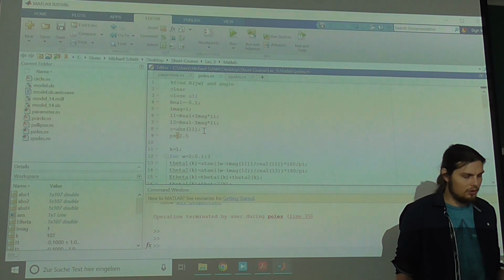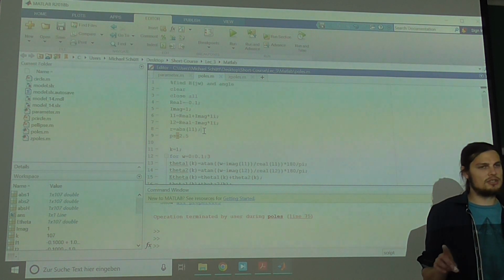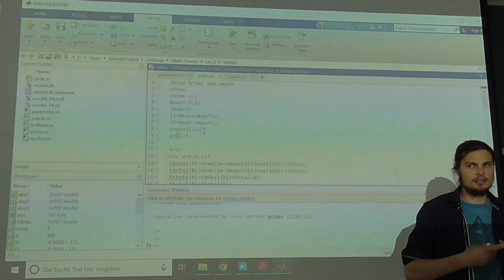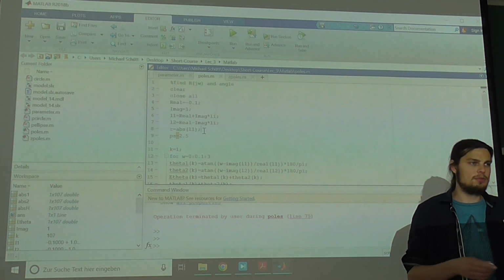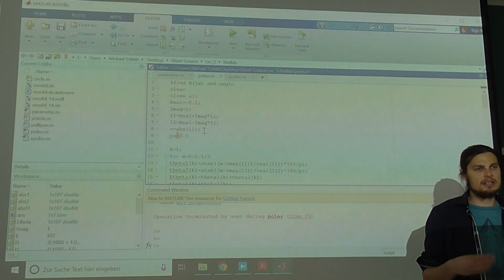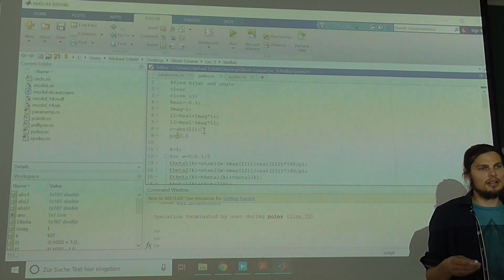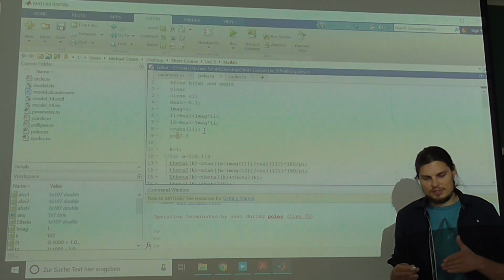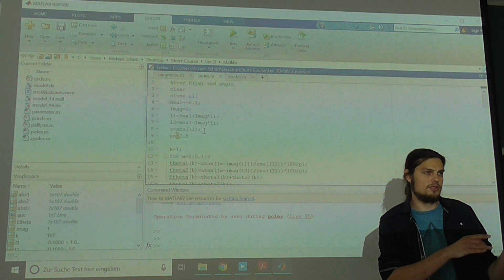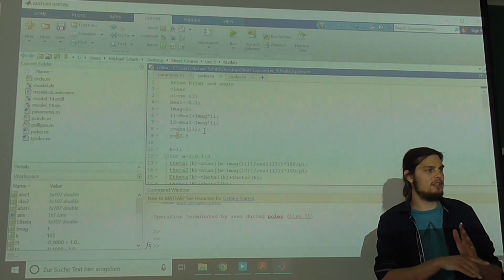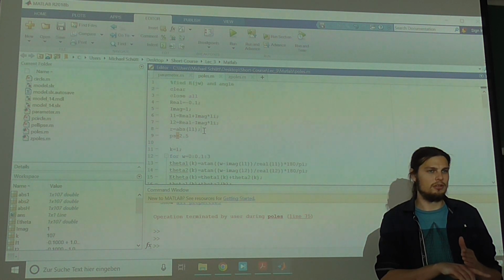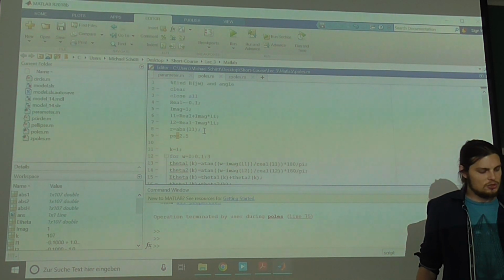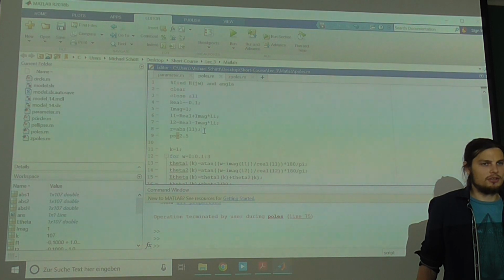So all the continuous stuff that we learn is still valuable and still great to know. In some cases, if you sample very, very fast with respect to your slow system, you can basically call it quasi-continuous, and then you can apply all of these ideas too. But if the tau of your system is too close to your sampling time, then you will see that your approaches won't work anymore. But this is something you have to experience yourself, so I want to teach you direct discrete modeling today.